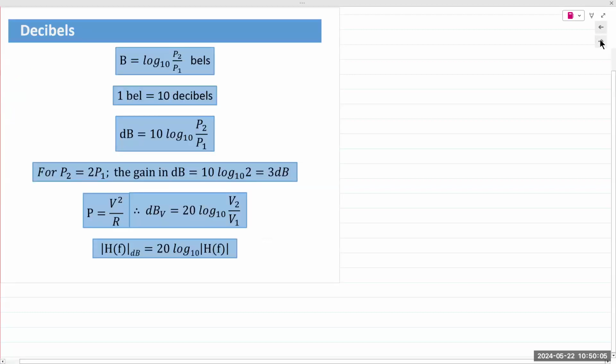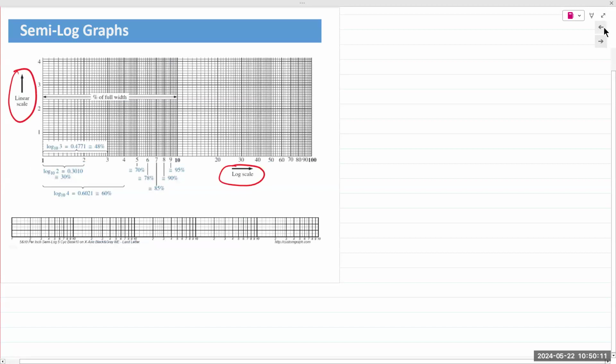Here. So again, this is known as a semi-log because one axis of the two is in the log scale, the other one is in linear. But in a Bode plot, both axes are compressed. Okay, the frequencies are compressed on the plot itself, whereas the y-axis, the data points, the magnitude of the transfer function, is compressed before we plot it. But both of them are compressed nonetheless. And what it does, it allows us to plot a very wide range of data points onto one single chart. And I will explain how.